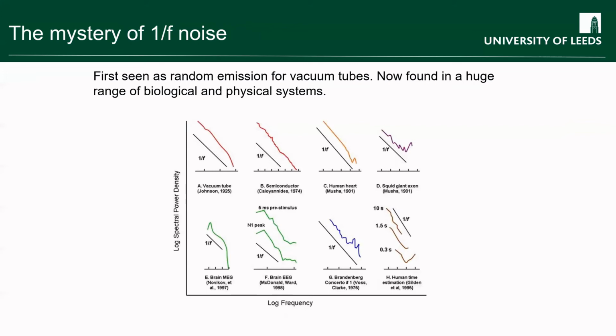However, even if you take all those things into account, what you then discover is that for probably nearly all measurements you can possibly do, there's another source of noise on top of this. And this source of noise has an amplitude which does vary with the frequency. So it goes as the frequency you're trying to measure, not the bandwidth you're measuring it in. The difference here is that this simply depends on the frequency of the measurement, but not on how long you spend trying to do that measurement.